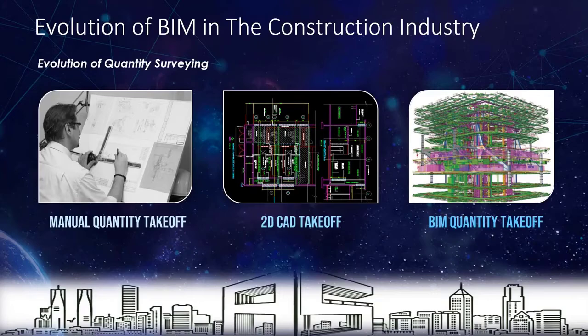And then eventually, you got into a place where you have 2D ready-made drawings available with you, and you start doing the measurements from there and do your quantity takeoff. So materials takeoff, quantity takeoff, we do all of this stuff right from that 2D drawing at that stage. Up until now, we are doing the same thing. But then BIM quantity takeoff came into the picture.